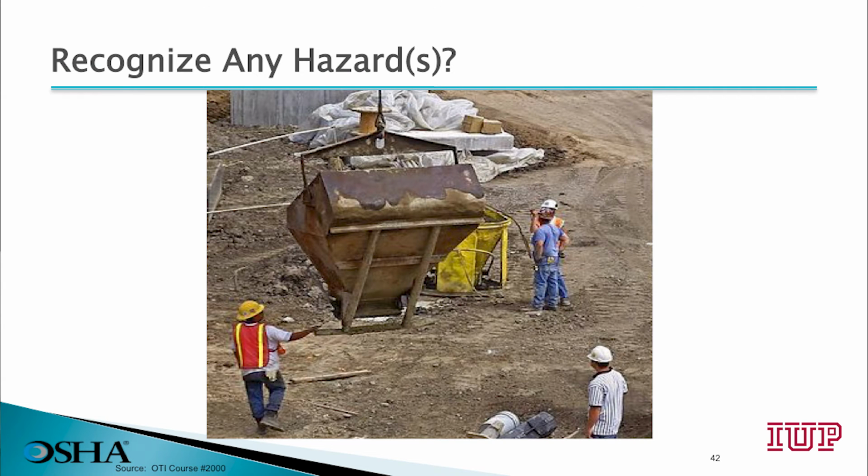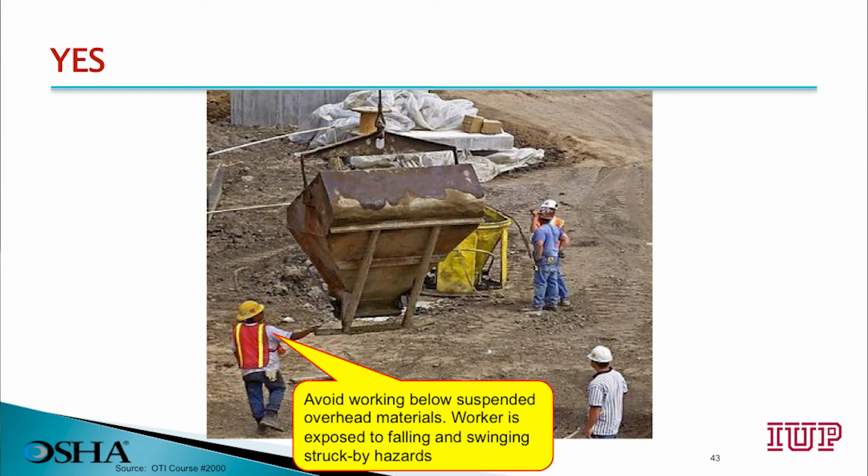On this job site, can you see any hazards? This worker is working below suspended overhead materials and is exposed to falling or swinging struck by hazards.